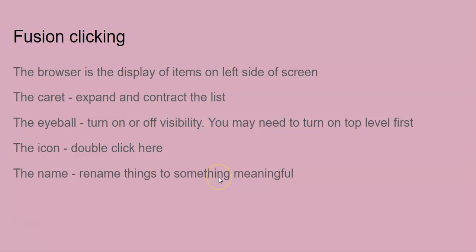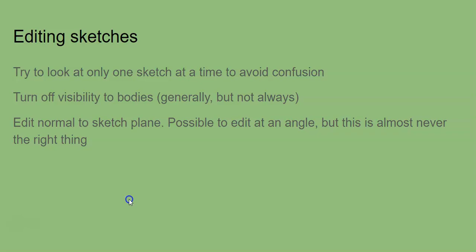Okay, we talked about Fusion clicking. Just, you know, the caret, the eyeball, the icon, and the name. It's important to rename things so that they're meaningful. Okay, editing sketches. What you want to try to do is have only one sketch visible at a time to avoid confusion.